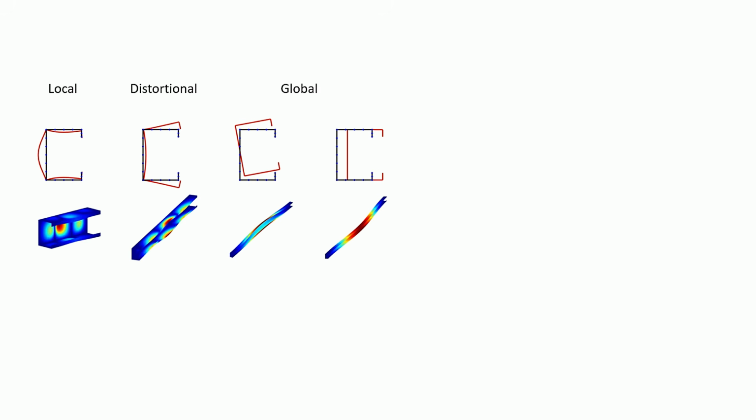That means compatibility and equilibrium at fold lines and element junctions are naturally respected. That is why DSM is so powerful for modern cold-formed steel sections, especially for lip channels, Z-sections, hat sections, panels, and members with intermediate stiffeners, where distortional behavior can matter a lot.